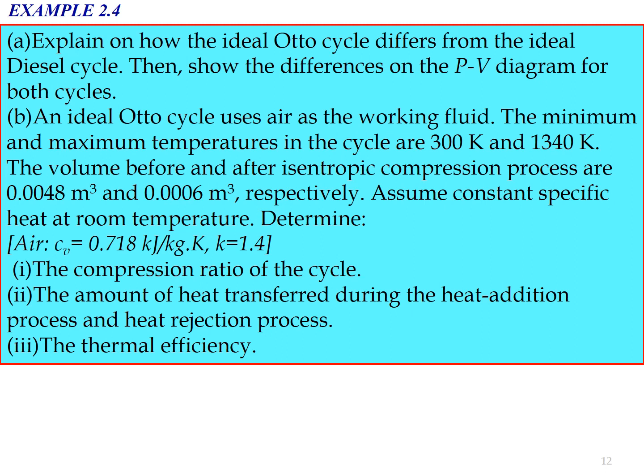Another clue that you can use to determine the case is that the question gives you the value of CV equal to 0.718 kJ per kg Kelvin and also the value of K equal to 1.4. If this kind of data is given in the question, you automatically know that the question asks you to consider the cold air standard assumption, where you need to use the CV and CP formulas, and you cannot use the ideal gas of air table to solve the problem.